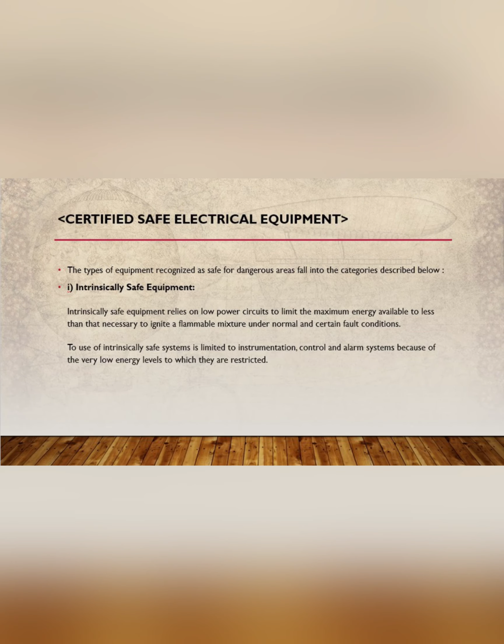Certified safe electrical equipment. The types of equipment recognized as safe for dangerous areas fall into the categories described below. First is intrinsically safe equipment. This equipment relies on low power circuits to limit the maximum energy available to less than that necessary to ignite a flammable mixture under normal and certain fault conditions.